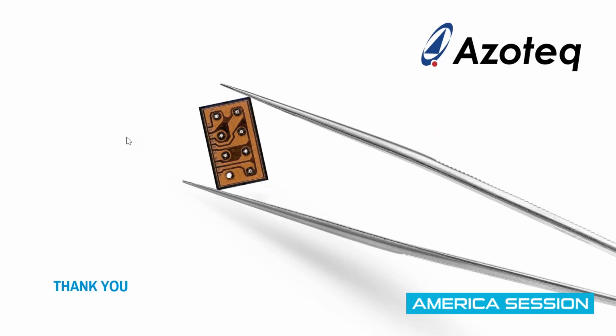So sampling at this low rate, 10 Hertz or 4 Hertz, we can drive the power consumption down on a single key, probably as low as 4 or 5 microamp in this low power mode. But that is fully configurable over the I2C interface. You set up a register the way you would want your power architecture to work. How soon to wake up, how soon to go to sleep.